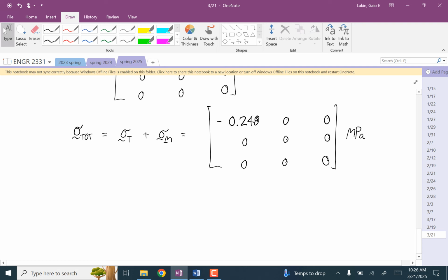So with the same amount of material, with a careful choice of what the cross-section is, we reduce the amount of stress by almost a factor of 10, or somewhere in that ballpark. And what that means is we can apply a ton more load to it before we're worried about permanent deformation or anything like that.